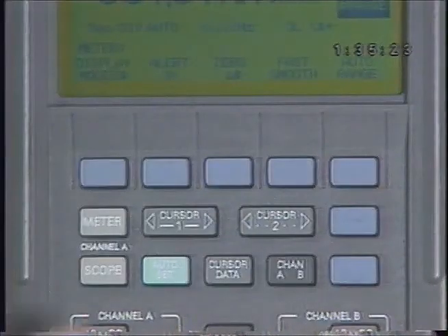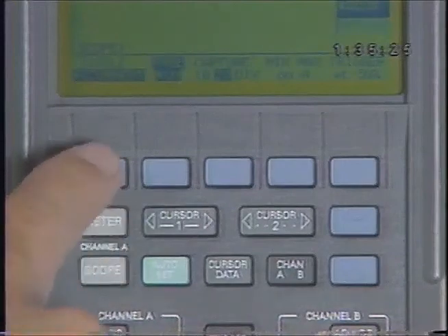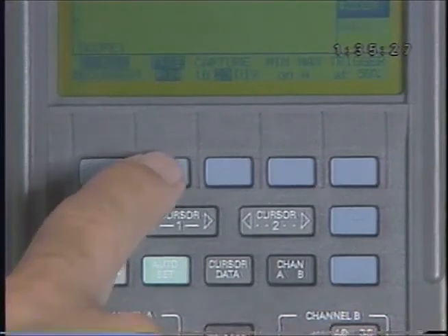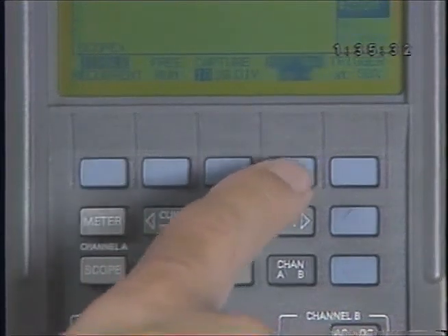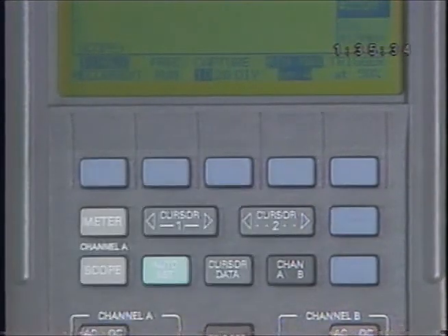Switch over to the scope mode and set Scopemeter to single. Turn free run off and highlight Capture 10 divisions. Activate Min-Max to raise the sampling rate to Scopemeter's maximum level.